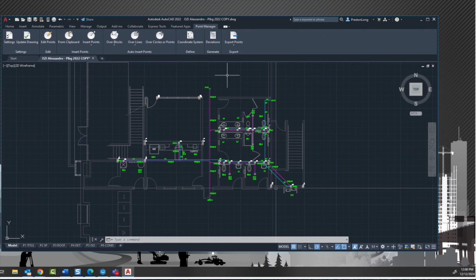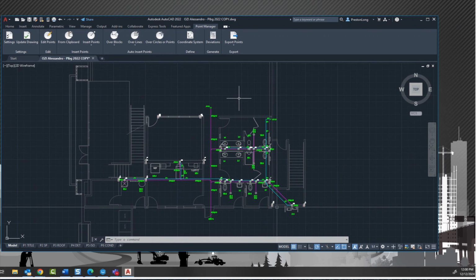What I usually tell a lot of people is ask the structural guy what they're using for control, because when they put the structure up and they're measuring off of something, and you're doing the plumbing and measuring off of something, you end up in the same spot. That's the key, right?